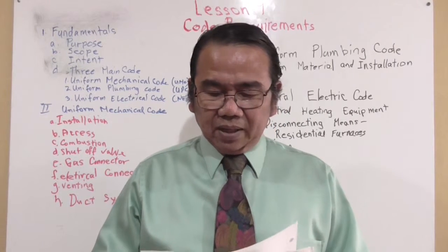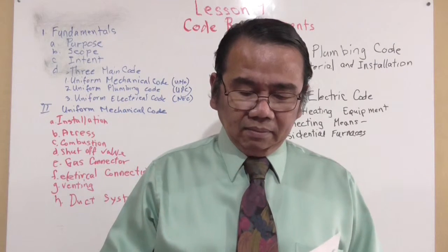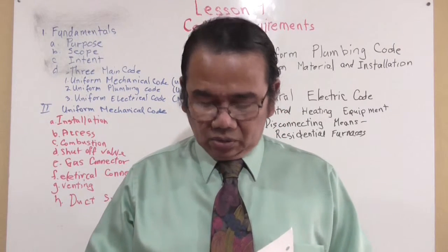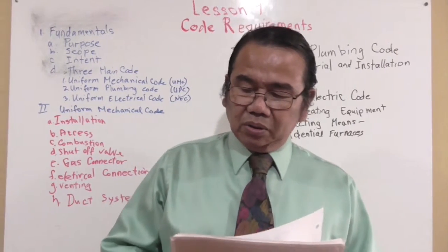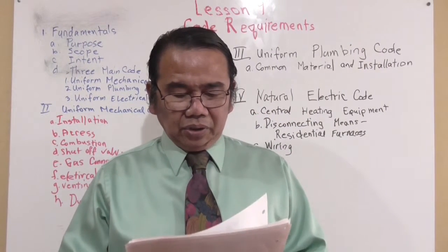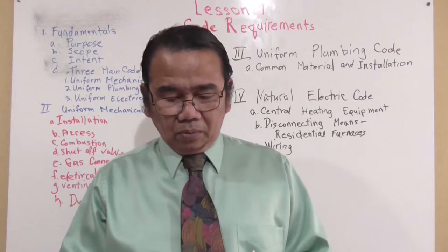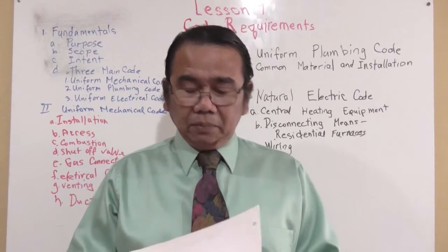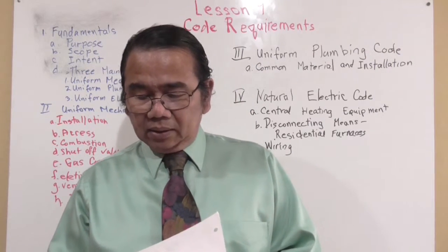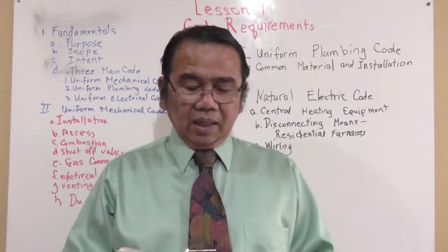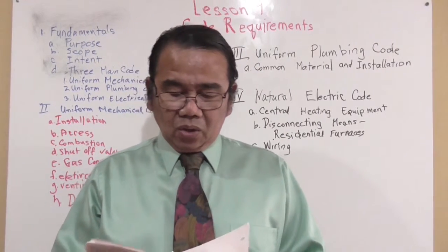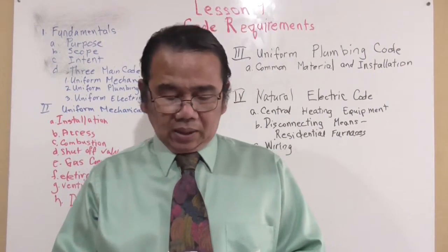Venting for gas fired systems. B vent: dual wall metal, no screws, locking joints, round or oval. And then BW vent: dual wall metal, no screws, locking joints. Wall furnace only.